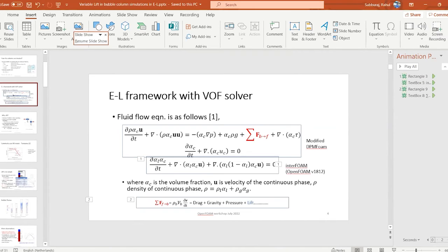It's a really good question because I didn't tell you why I'm using it. There were simulations which were using only the Lagrangian solver, but the problem is when the particles move out of the domain, the fluid is also dragged along with it. To avoid that, we keep a free surface. That is mass conservation inside the system. Does that answer your question?